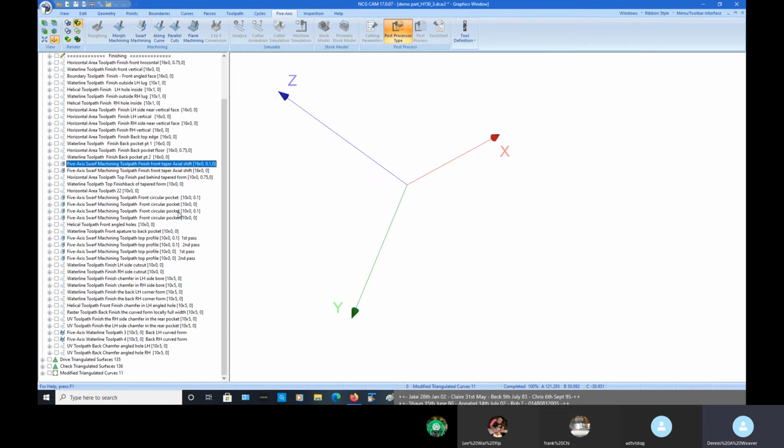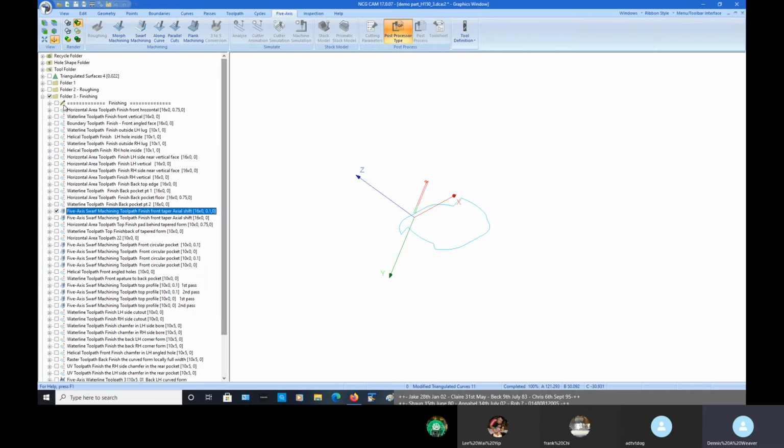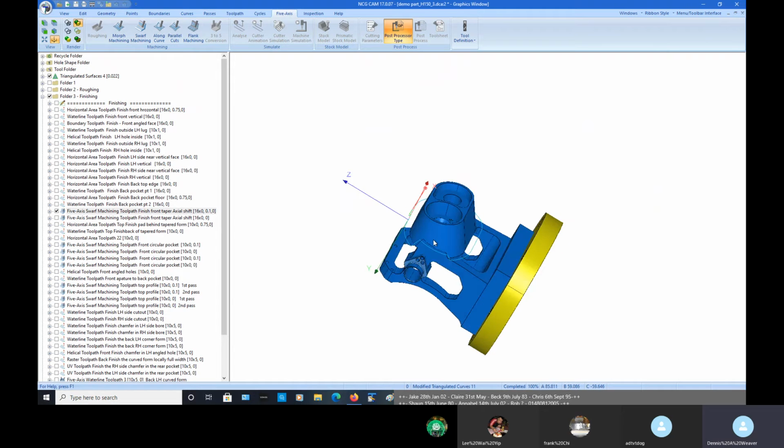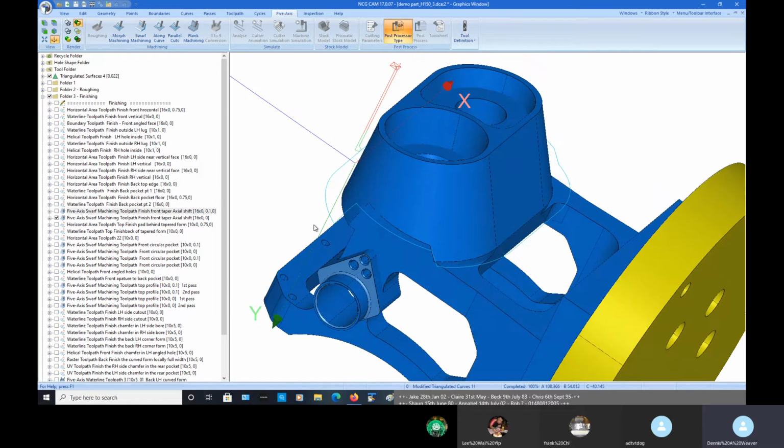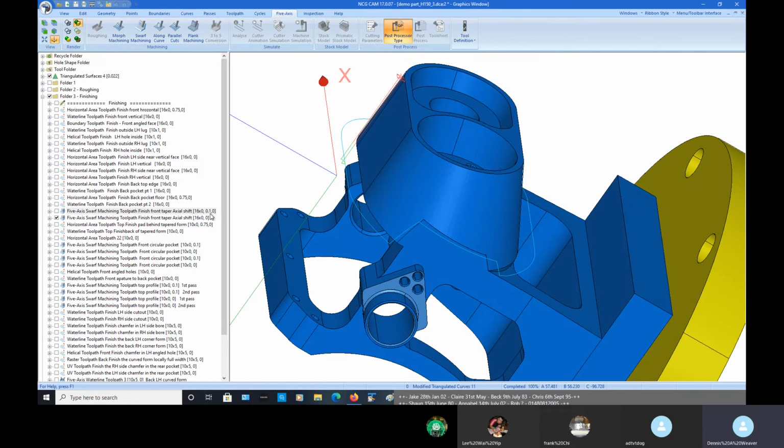So the toolpath created by the swarf machining goes around the outside edge of that. We've also got similar swarf machining, taking some extra material off. So the first one went round with a 0.1 thickness on X and Y with a 0 on Z, and then the second one goes around and takes a spring cut around there in order to remove the final amount of material.